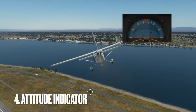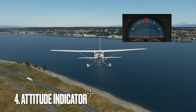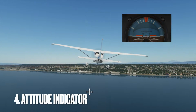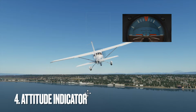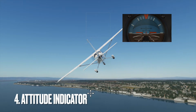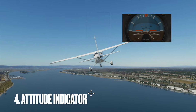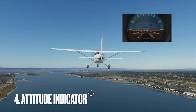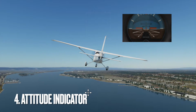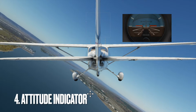The attitude indicator, also known as the artificial horizon, provides information on the aircraft's pitch and roll attitude relative to the horizon. Pilots rely on the attitude indicator for maintaining aircraft attitude, especially in low visibility conditions or when flying solely by reference to instruments. During instrument flight, the attitude indicator helps the pilot maintain a level attitude despite visual cues being obscured.